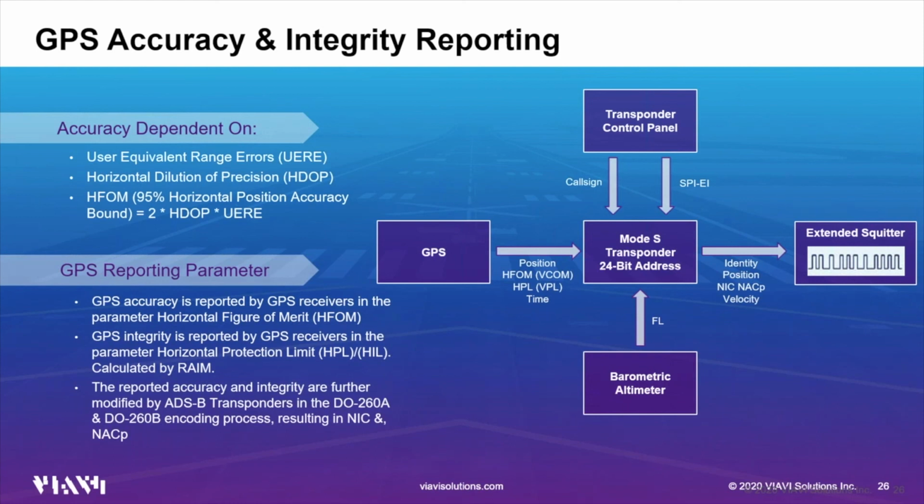Now, when it comes to reported accuracy and integrity, for GPS receivers which are not SA aware, the accuracy and integrity reported and then used in ADS-B messages is based on an assumed value of UERE corresponding to the period when the SA was active. This value can be grossly larger than the accuracy of the positional data delivered now that the SA is inactive.